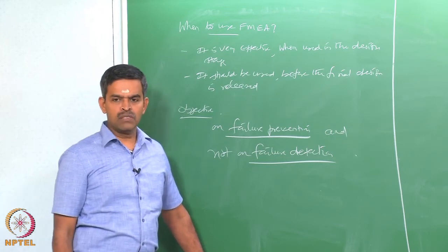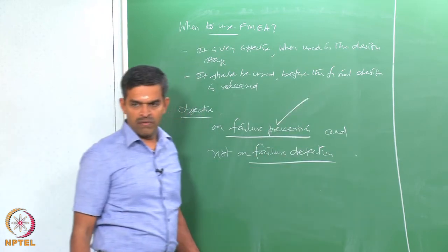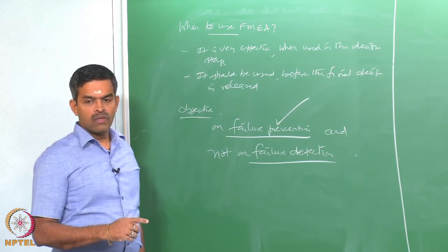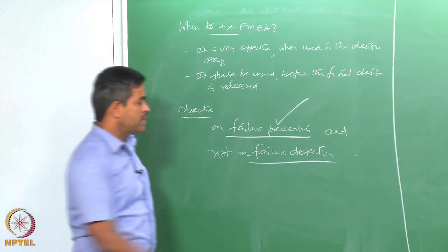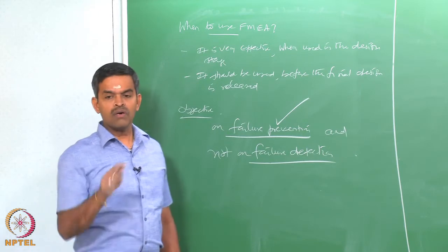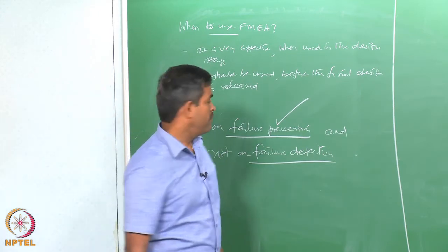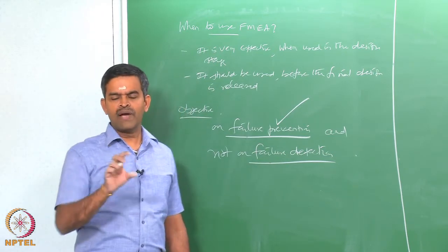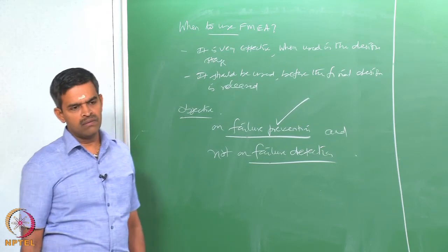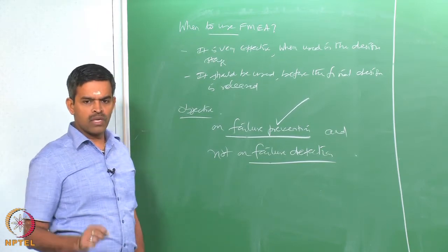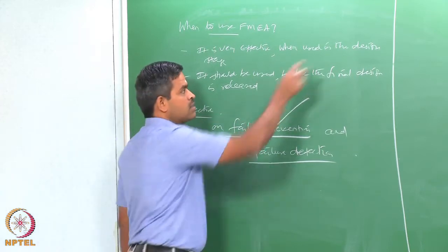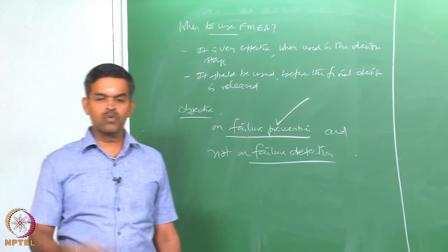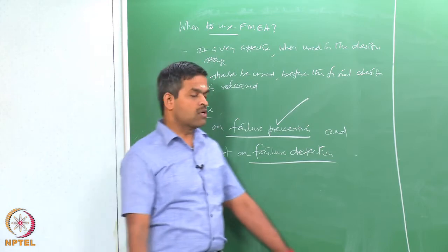It is very effective because it works towards failure prevention itself, whereas hazard analysis tries to find out what are the possibilities of occurrence of failure. So, it is detecting the failure, then you have got to take steps to avoid that kind of failure, whereas in FMEA study it directly addresses the critical factors which should be corrected, which should be modified, so that the failure is prevented at the design stage itself. Therefore, friends, FMEA is considered to be one of the most effective tools to assess the performance of electromechanical systems.